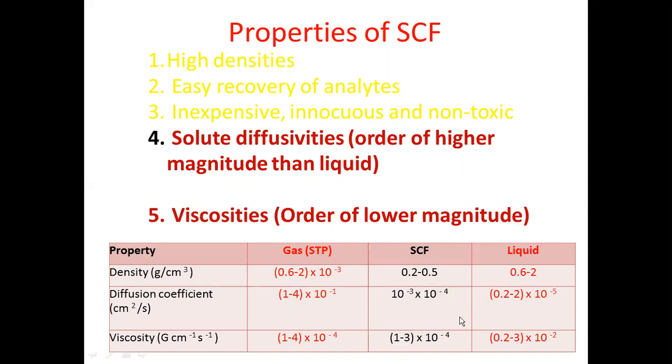This larger diffusion coefficient of supercritical fluids will make easy dissolution of the components or the solutes in supercritical fluids. So therefore, because of the intermediate value of diffusion coefficient of the supercritical fluid, the solubility or the dissolution rate of the substances in supercritical fluid will become excellent.